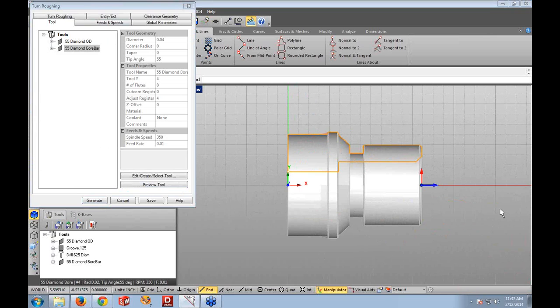While he's doing this, you have the ability, all the same operation parameters for ID roughing. In fact, it's the same operation. You just specify a different tool, such as a boring bar, that has an appropriate orientation for the insert, as you'd expect. And also specify that it is ID work, and the system will be able to rough out any region within the inside of the part.